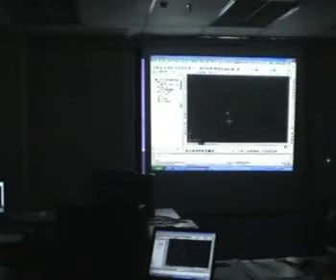If I need to reposition this text, maybe sometimes in a drawing you have the text overlapping boundaries of your platforms, for example. You can just click on this marker and drag. I'm going to zoom out. You can see no matter how far I drag my cursor away from the contour line, the text still follows the contour. So this is about contour lines for Autodesk Land Desktop.